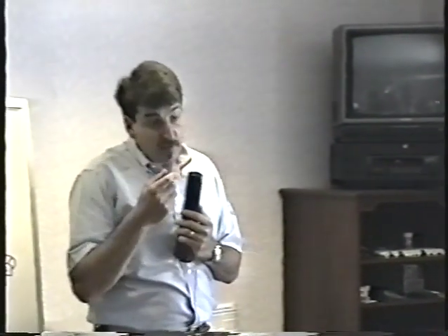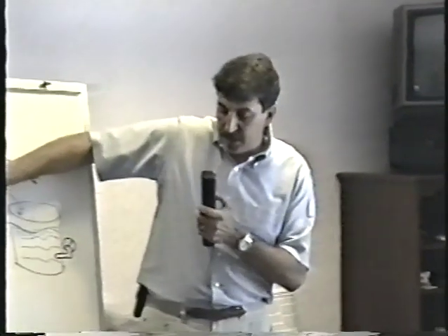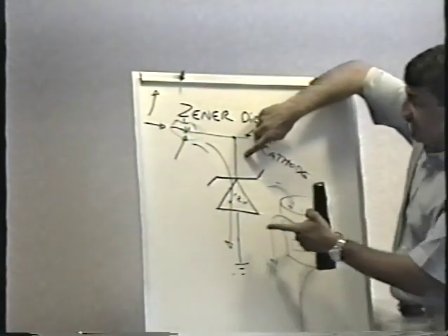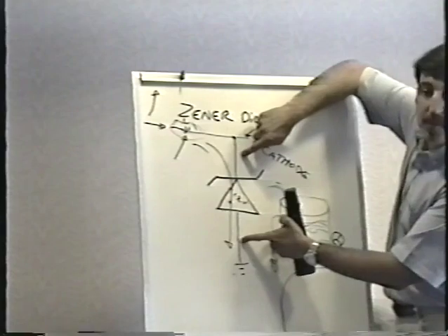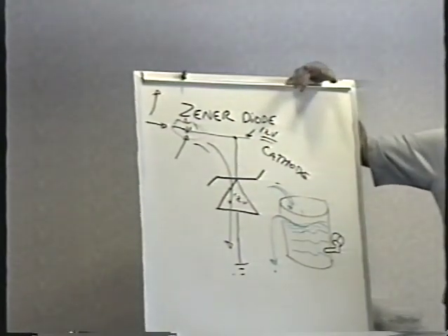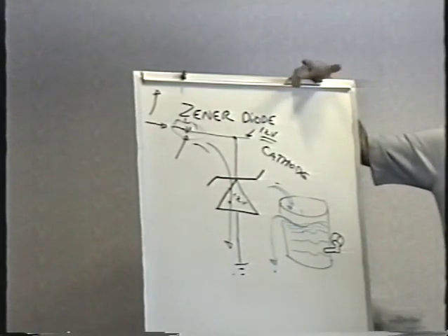And this is what happened to me. So I say, well, I've got a regulator problem. It's got to be one of those transistors or Zener diodes in there, and I check them all with the power off, as you should do. They all check perfectly okay. Next step, turn the power on, and carefully check the voltage across the Zener diode. Put one meter lead on one side of the Zener, the other on the other side, measure the voltage across it. If it's a 100 volt Zener, it should have 100 volts across it. In this case, it only had 40 volts across it. The Zener was bad. I changed it, and that's all there was to it.